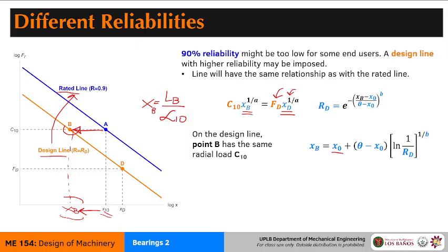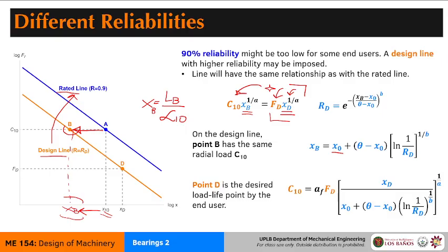So the design side, the right hand side here, is what the designers intend, and one way to use this equation is to arrive from the design side, what the designers desire, to the manufacturer side, which is what rating of bearing should I buy. So based on the design, we figure out what bearing we should buy. Meaning we find out what C10 rating should we get and whatnot. In order to cross that bridge, we just do some rearranging.